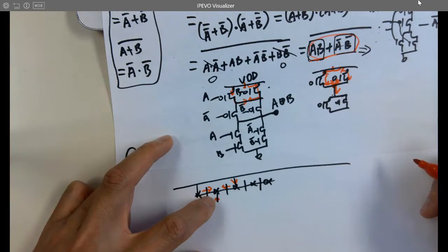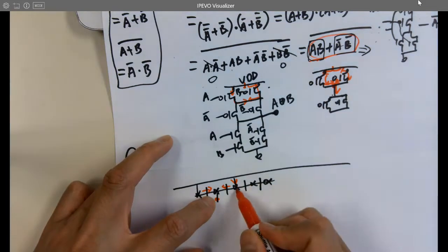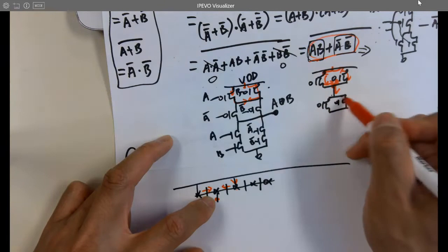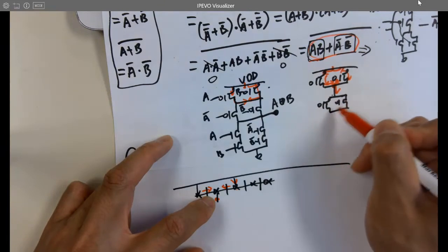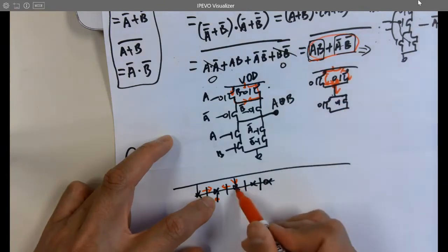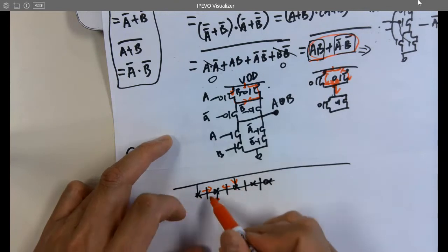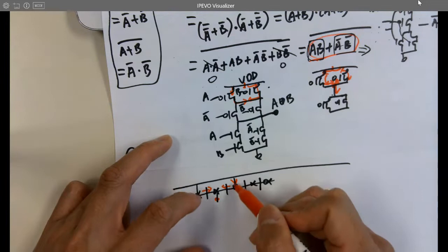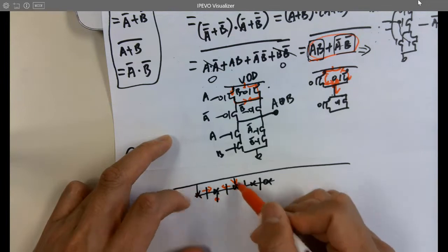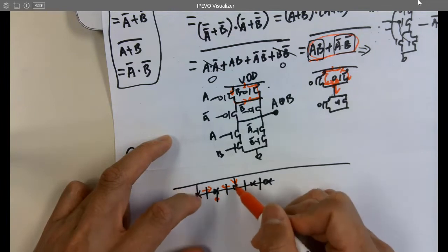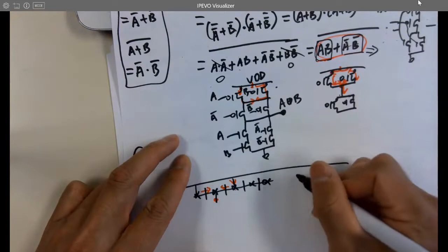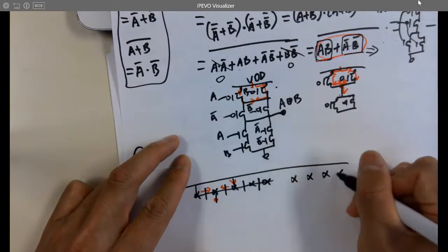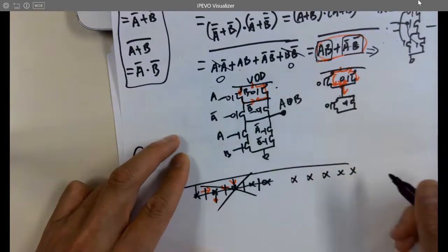It's not going to work. Why? Because the VDD is shorted to these 2 transistors, so they don't have any proper VDD connection. As you can see here, these 2 transistors have one of the nodes shorted to VDD. So at the very beginning, when I was designing the parallel PMOS, I shouldn't have done it that way. I have to change the strategy here. So this doesn't work.